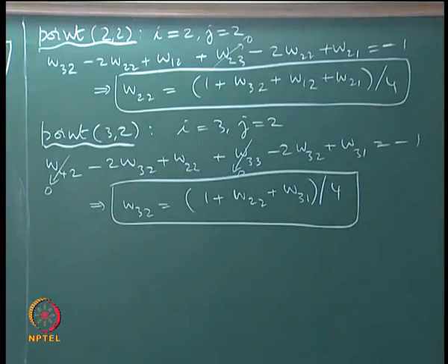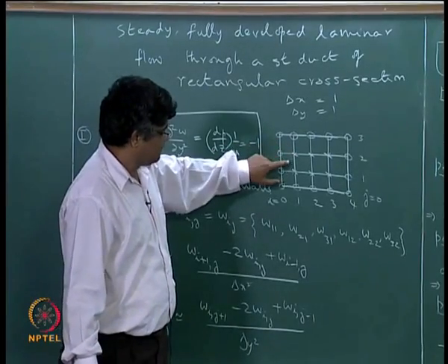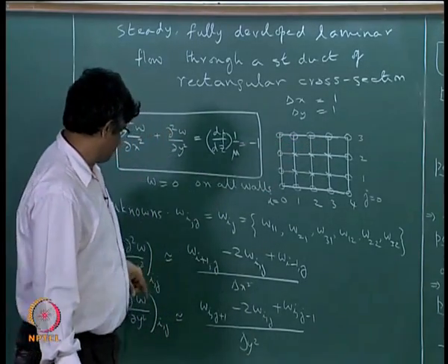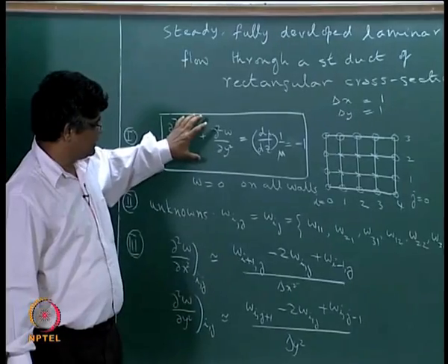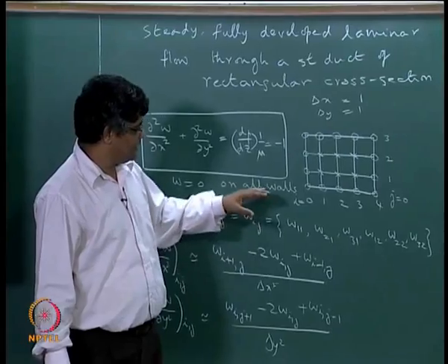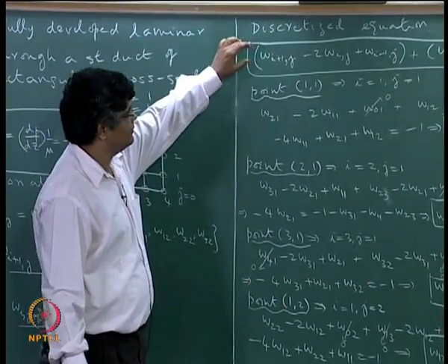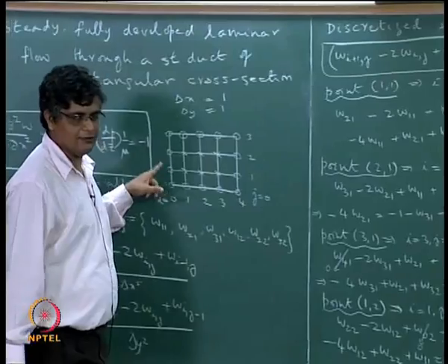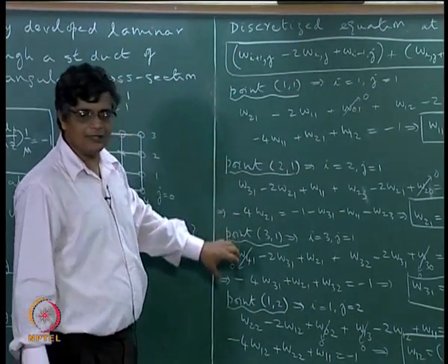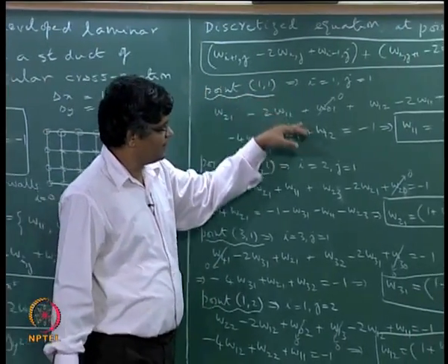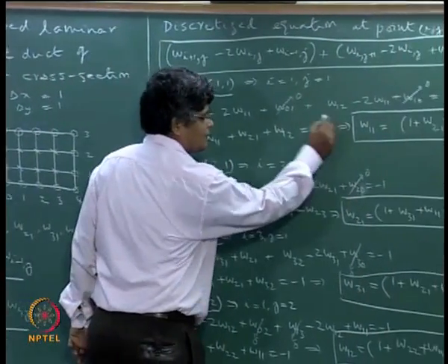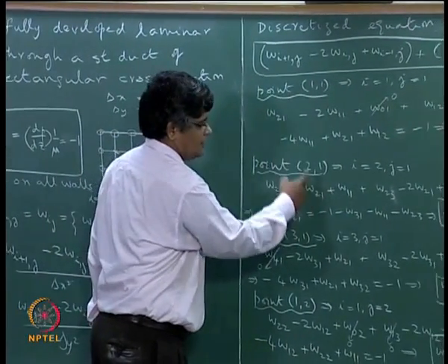So by approximating at each of these discrete points at which we want to get the solution, by approximating the partial differential equation with finite difference formulas and coming up with a template here after substitution of delta x and delta y and the constants like this, we take this template and apply it to each point at which we want to get a solution, and from that template we will be able to derive the corresponding algebraic equations which give us the values.